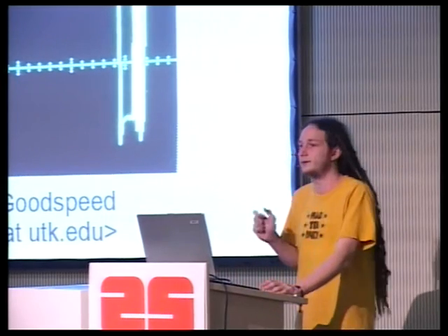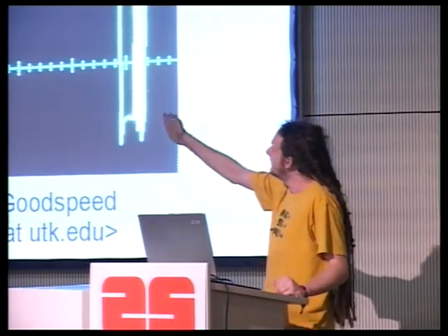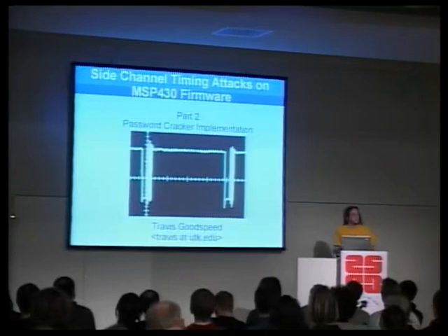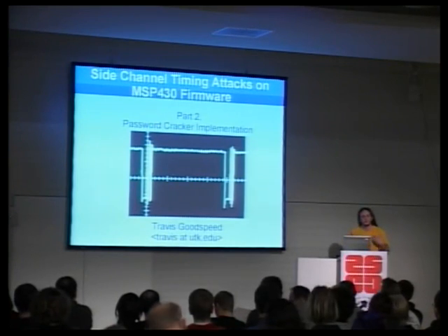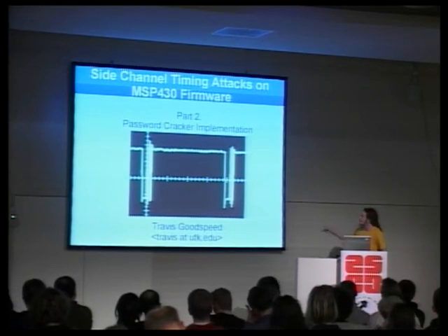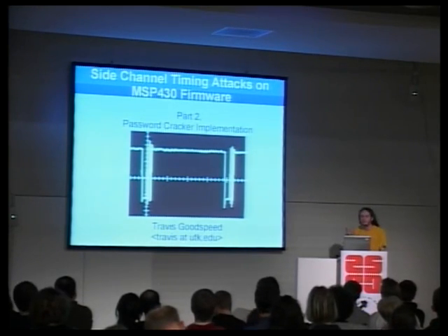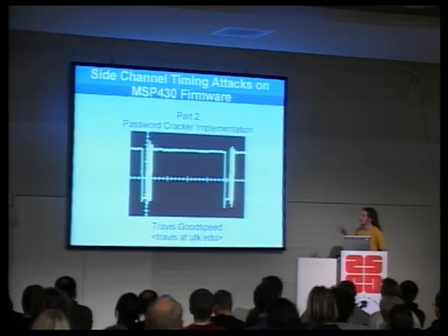The basis of the attack, though, is in the timing of a password comparison. If you look at this waveform on the title slide, the left is an acknowledgement telling the attacker that it's okay to transmit. Between the two signals, the attacker is giving a password guess, and he's doing it with non-standard serial timing. Then the right waveform is the victim telling the attacker that the password is wrong, and that he's not going to be given access to protected memory.